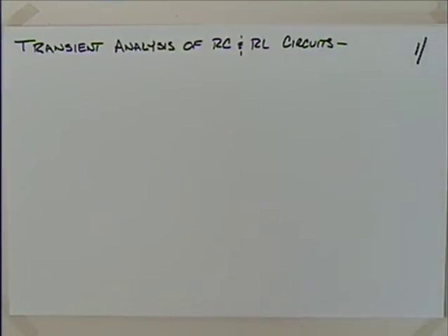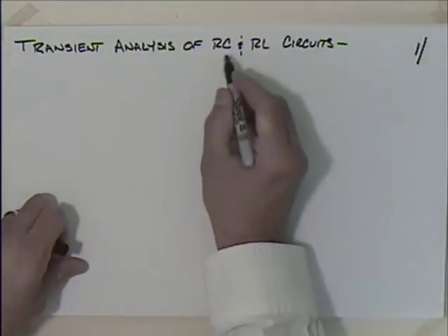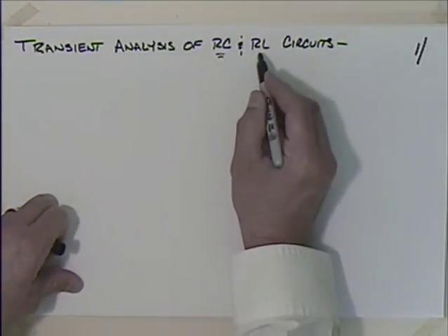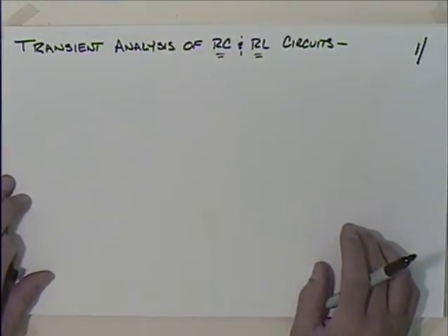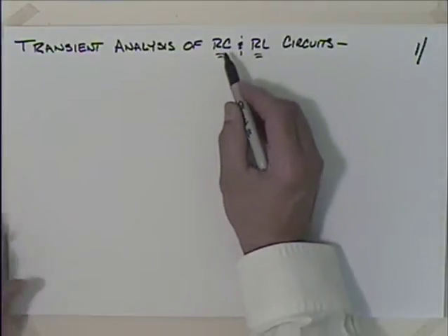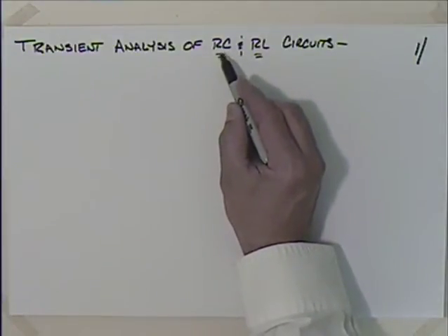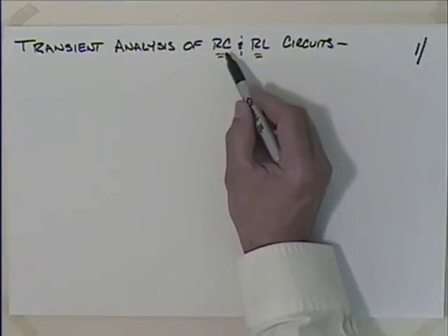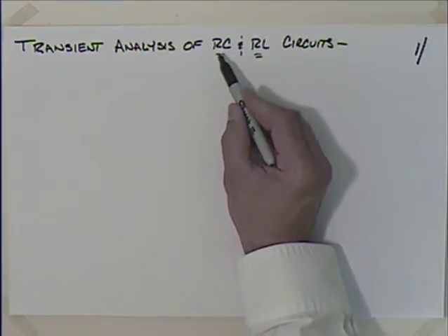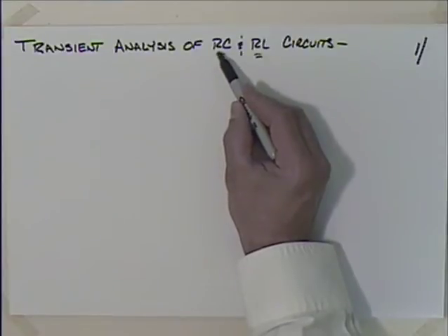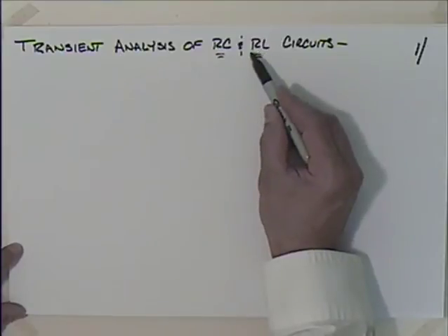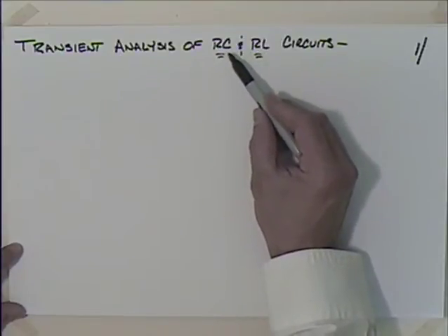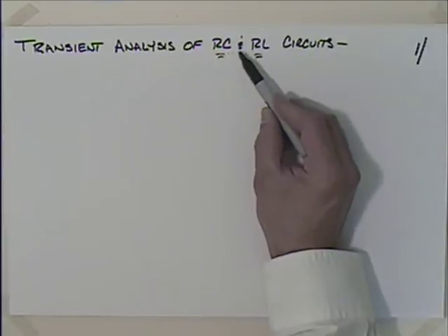So, with transient analysis, we're going to look at RC circuits, so the analysis of RC circuits, resistor and capacitor circuits, and RL circuits, resistor and inductor circuits. And one of the requirements is that we have only one energy storage element. So in fact, if it's an RC circuit with multiple capacitors, if we cannot combine all of those capacitors into one capacitor, we're actually not going to be able to do that. So we're fairly limited. It is going to have to be resistor capacitor circuits, or resistor inductor. And in fact, because I can only have one energy storage element, we could not do RCL circuits.